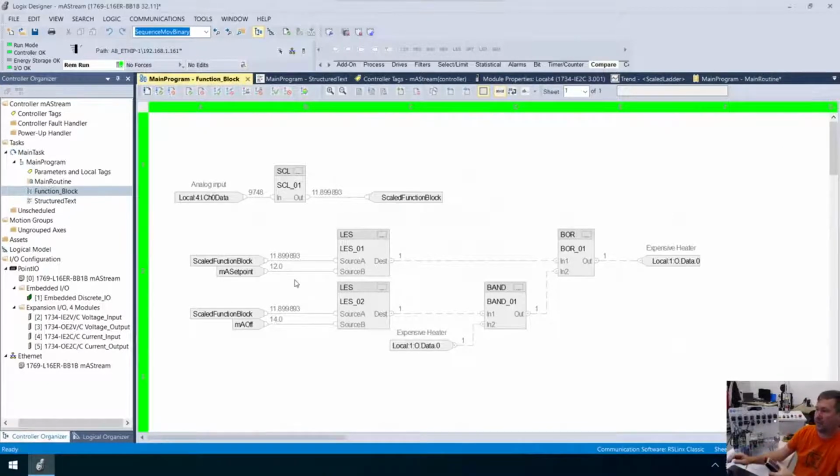Our green is on. And we are at... So right now, our milliamp value is less than 12. So this is true. And it's represented really well by this 1 right here. So we know this is true. And then we have an OR statement here. Now it doesn't skip still. There is a process that goes through, and I'll show you later in some function block exercises why it matters. But okay, this is also less. So this is true. It's really shown well by that 1.